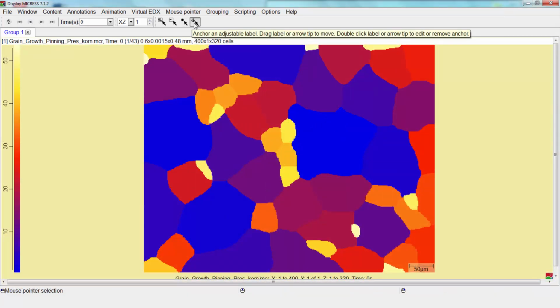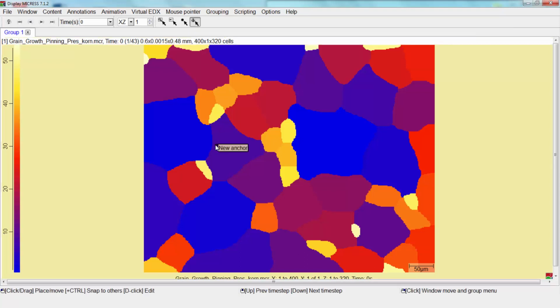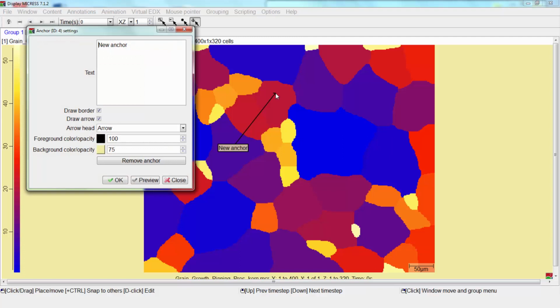The anchor gives a reference value to another point. One click places the anchor, and to define the anchor's position, it can be moved to a desired point. Beyond, by clicking on the arrowhead, the anchor's target position can still be changed. A double-clicking on the arrowhead activates a popping-up window which comprises several designing opportunities and moreover the possibility of deleting the arrow.